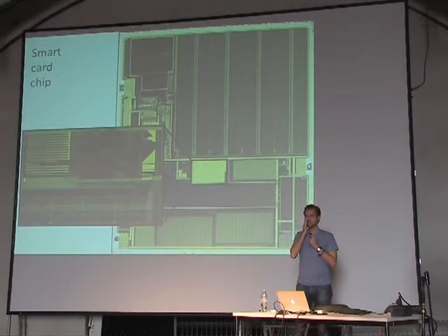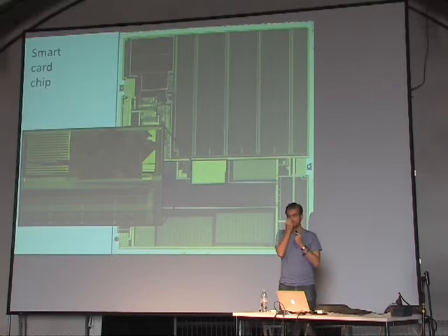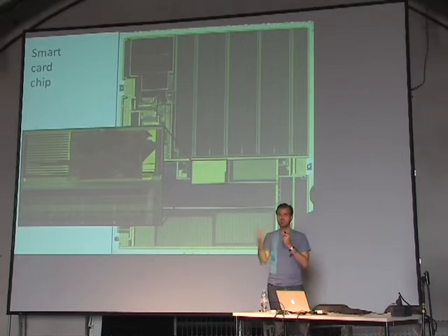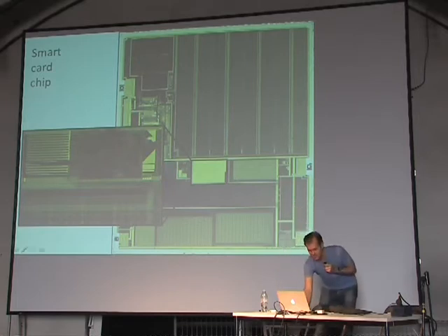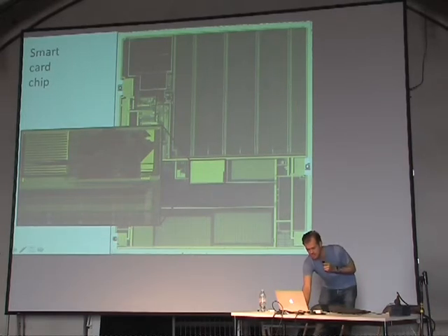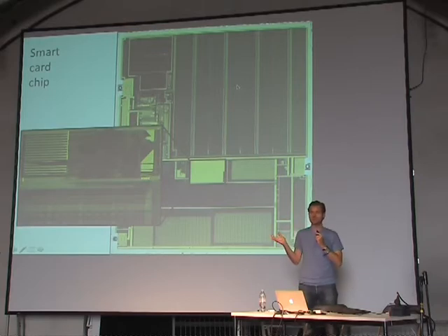So newer chip designs that don't have ROM masks but store their application code in Flash, those chips would mitigate these attacks entirely. They would, but there's really only one chip I can think of, and it's advertised as a rapid prototyping chip, not so much a production chip. This chip has 224 kilobytes of ROM, I believe. That's the small area down here. And it has maybe 70K of flash. So if you were to convert all the ROM into flash, this chip is more than twice the size, or maybe 3 times the size.